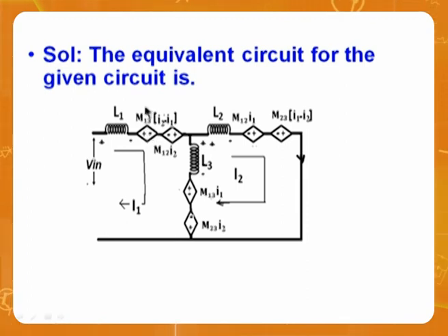First, mutual EMF due to what currents? I2 minus I1. And this mutual EMF due to what current? I2. So, on each coil we have two induced EMFs. That's very interesting. That's why this is the most complicated problem in coupling circuits, or in fact the total network theory.